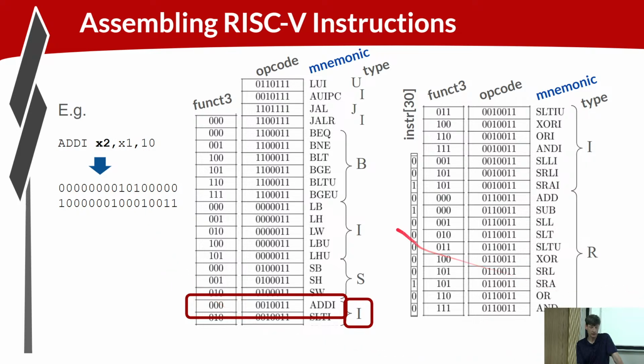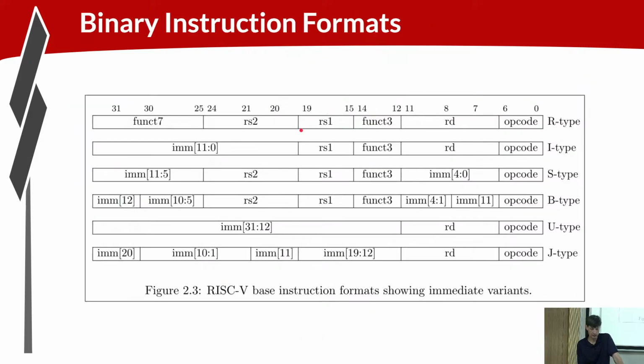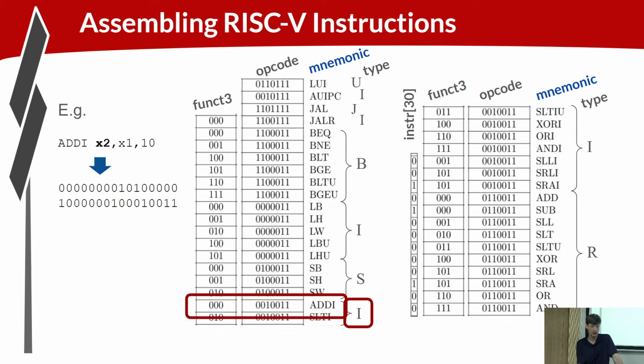This table is how we're breaking down to the specific instruction. I guess I lied before. We break down to the instruction from the opcode and funct3 for the most part. I think there's only one bit of the funct7 field that sometimes is used to specify the specific instruction type. So this table uses the opcode, funct3, and sometimes this funct7 bit, or instruction bit 30, to define which instruction we're talking about.